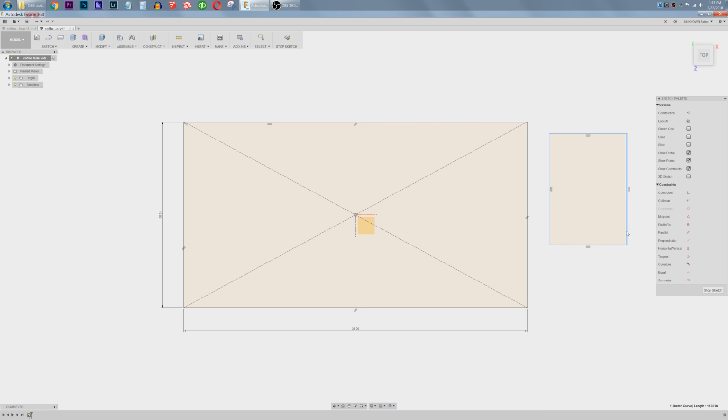So I can't change the angle here because they are already constrained. Now I can add dimensions to these, and they'll start turning black and defining them in space. Like this one just turned black. Now all of them turn blue when you hover over them, but fully define your sketches, make sure everything is black, and you'll have a lot less problems.